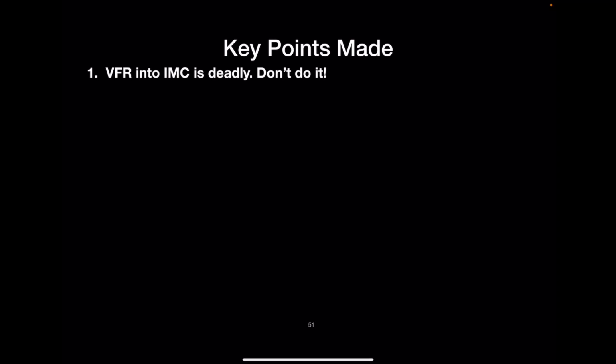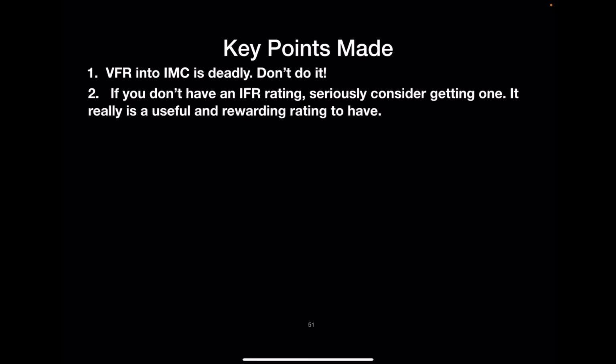VFR to IMC is deadly. Just don't do it. Remember the 3 minutes to live rule. Even if an IFR rating is not on the cards for you, when you go up for training, practice some basic instrument flying so that if you do find yourself in this situation, you can safely maneuver back to VMC.